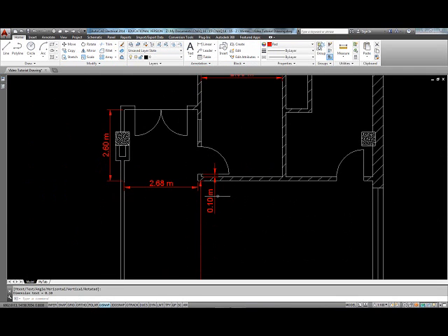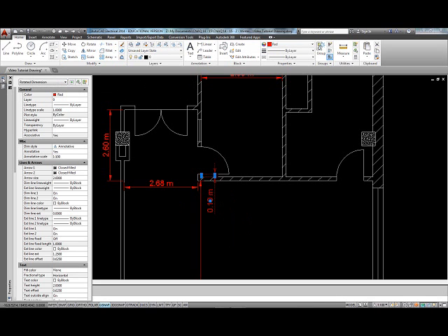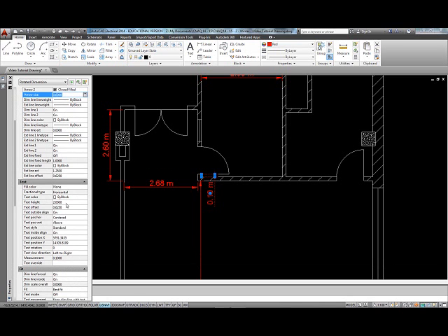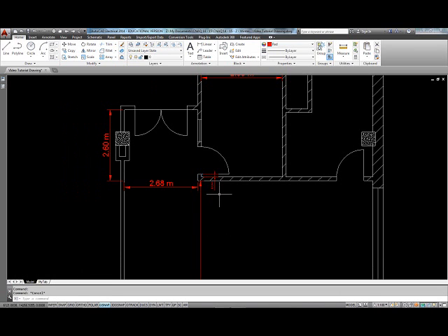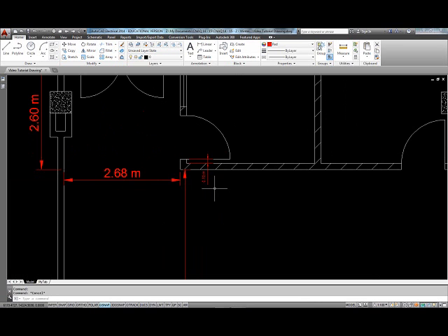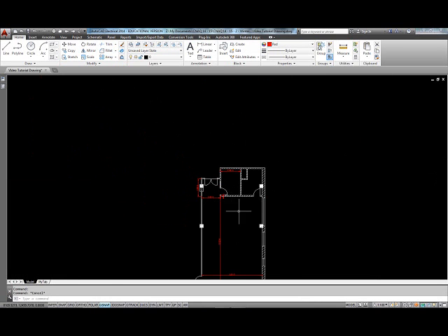However, you can change the dimensions for individual components by changing the individual items in the properties window. So let's say, for example, 0.6 for arrow size, and let's go down to text and make that 0.6 as well, and there it is. See, now it's small, but when you zoom in, you can see it.